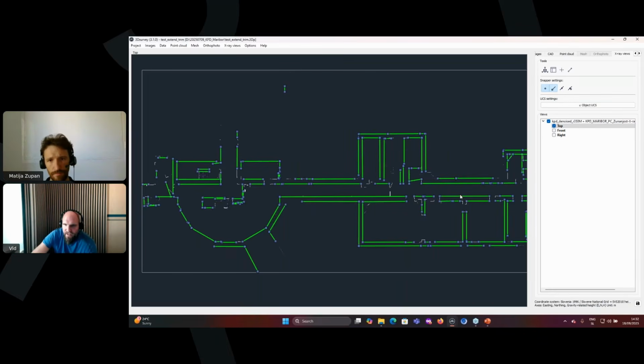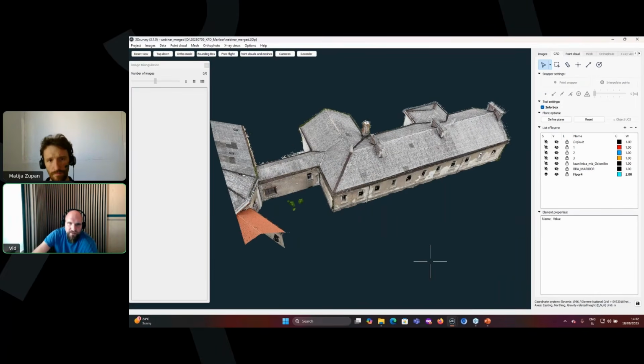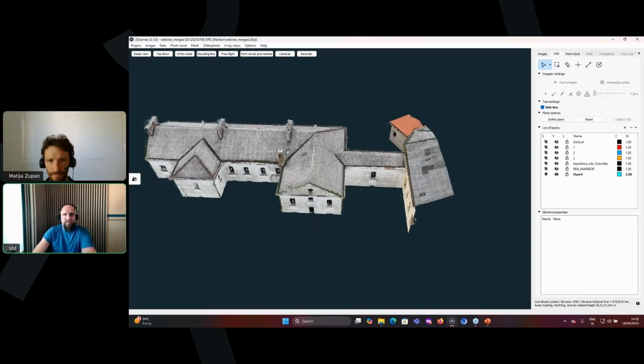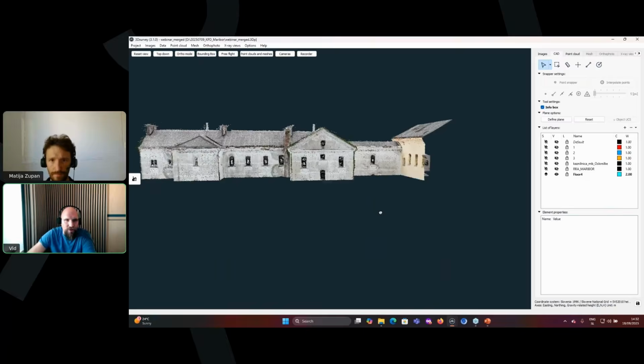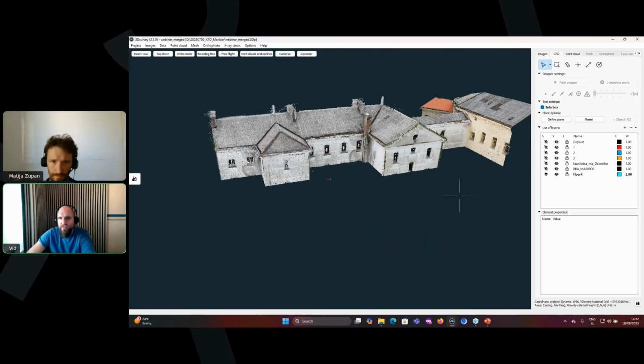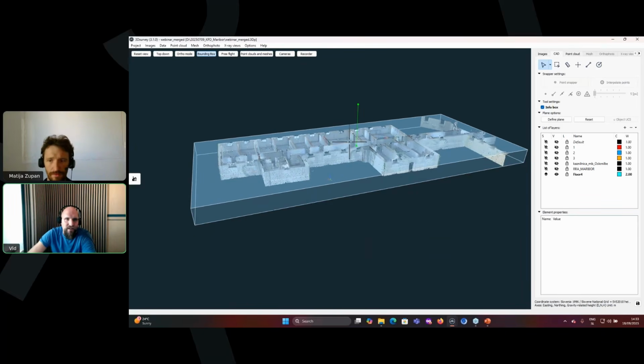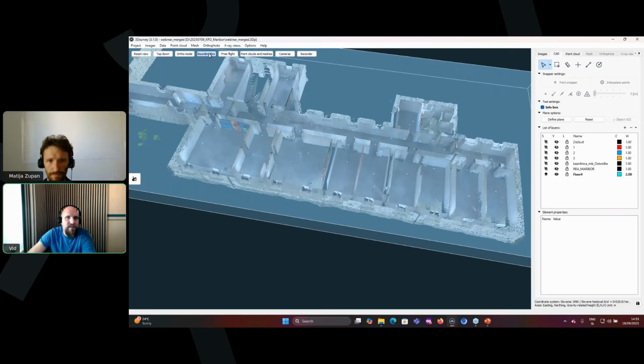Here, the institute needs the BIM model. And one thing about a BIM model is that if the room is approximately perpendicular, they need to have perpendicular angles in this room. In this case, using just the simple CAD section of 3D survey is already super beneficial. So here I now have a project where I only have the top floor of the building. For this demonstration, we'll just be focusing on the top floor of our area. To help with the digitalization, we will temporarily use the bounding box so that we have about a 2-meter high section of our building. Let's clear this one now.